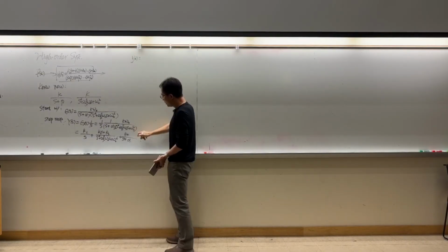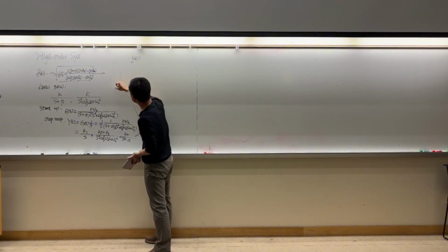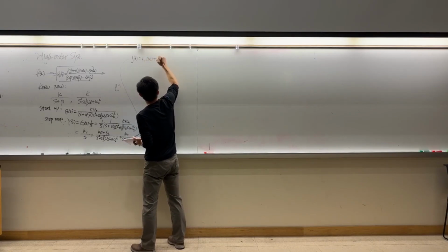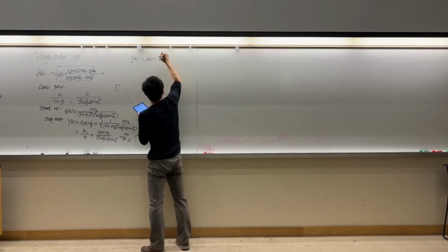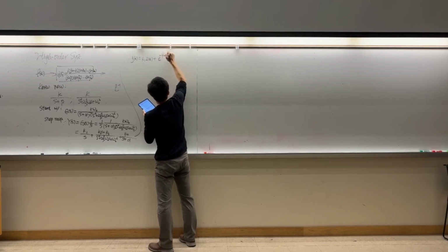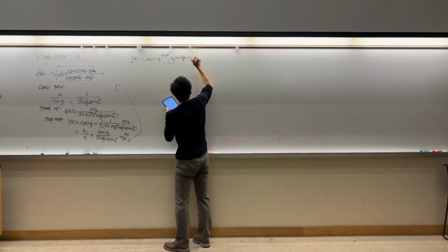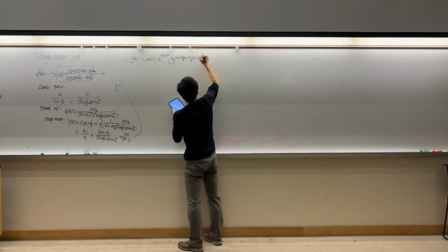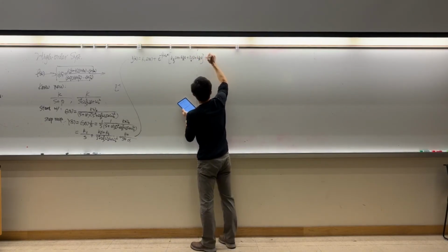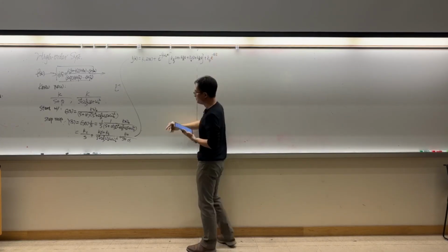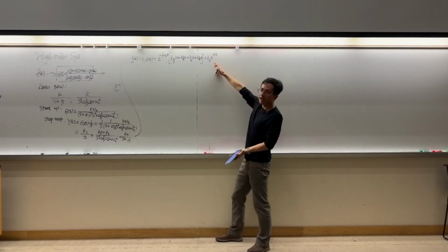Y of t will look like, because of this and going through inverse Laplace transform, we're going to have K1 times 1 of t, and then I'm going to use e to the negative zeta omega n t, with sinusoidal components inside, and I'm going to use K5,